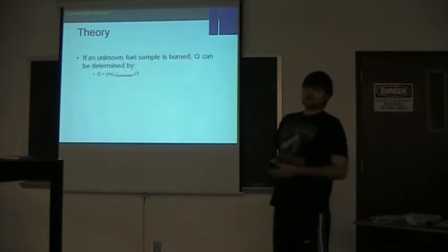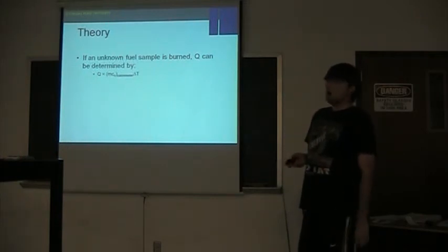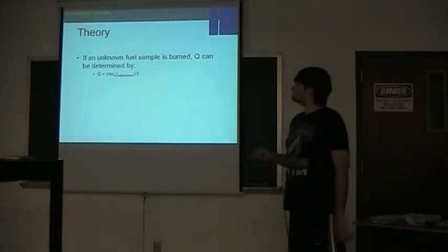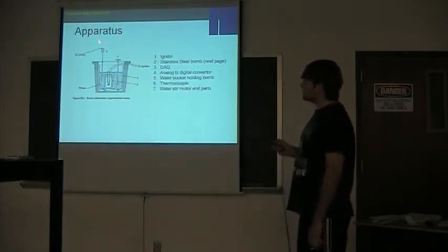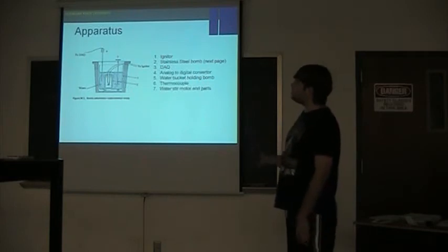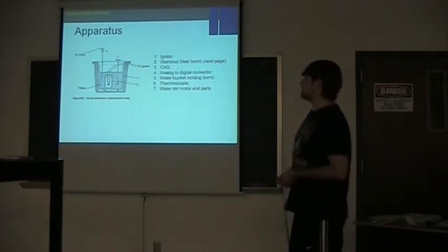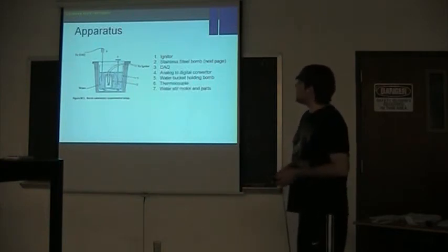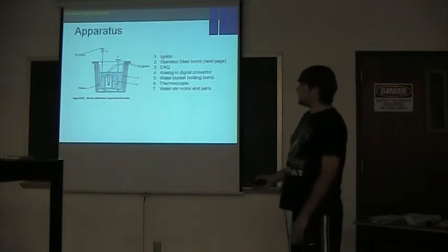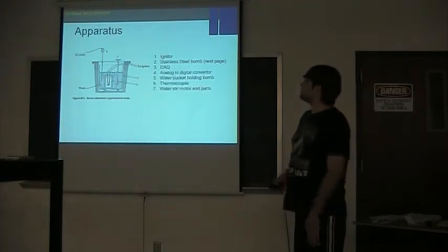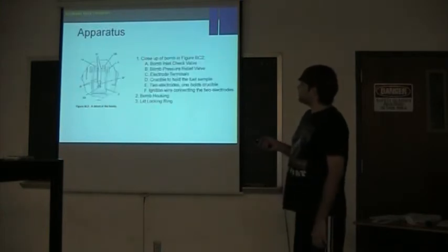In this experiment, we also will burn an unknown fuel, and to determine the value for Q, use the equation above. So, apparatus: at the top right here, you can see that's your thermocouple. The DAQ is connecting to the computer. It's software that records your temperature measurements. The bomb is in the middle right here. The next page you'll be able to see it more in depth. That's your water jacket, your bomb goes in your water.